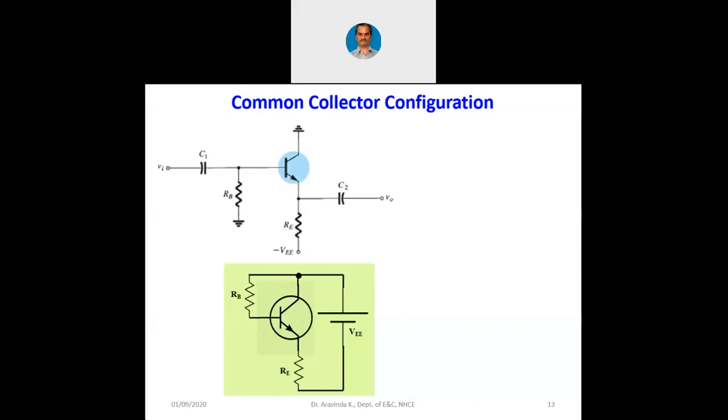called linear integrated circuits. There you are going to study more about the operational amplifier. For some operational amplifier circuitry, we use a dual power supply. Dual power supply means we will be using plus VCC as well as minus VEE along with the ground. We will have plus 12 volts and minus 12 volts along with the ground. At that time, we say with respect to ground, one is at plus 12 volts and the other is at minus 12 volts. That is the basic understanding of the power supplies.